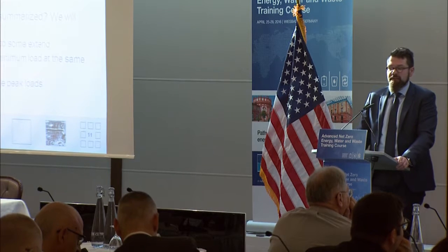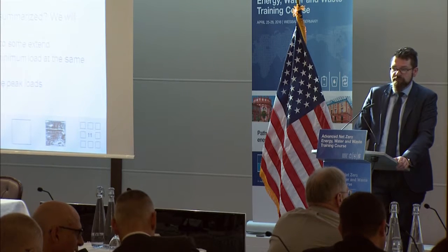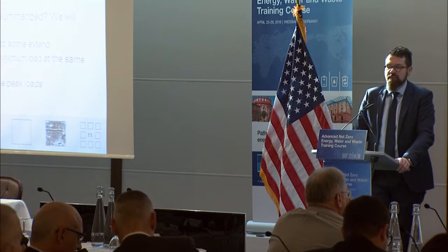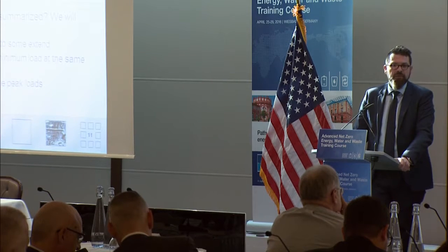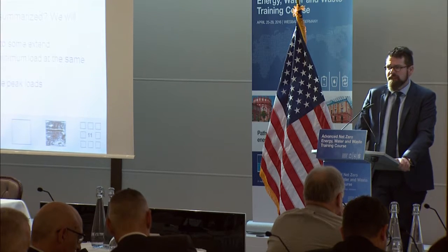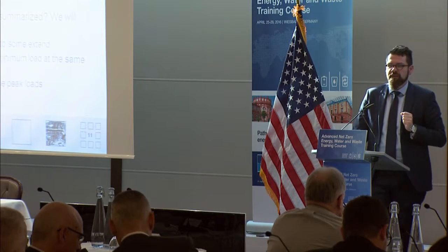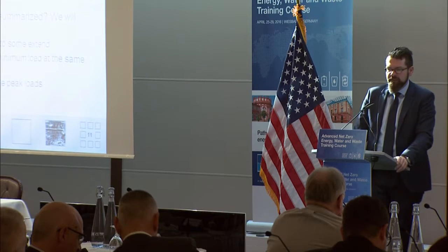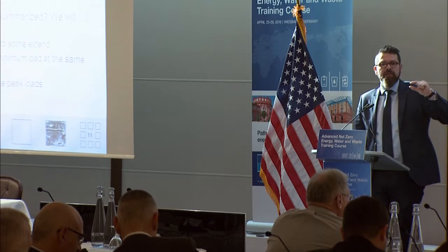Not all buildings have their peak load and their minimum load at the same time, and the total load, when you summarize it, is less than the sum of the single peak loads. This is a very important thing. If you have 3 buildings with, for instance, 100 kilowatts each, and you put them together, and the peaks are not at the same time, the peak load is not 300 kilowatts, it's, for instance, 250 kilowatts. So the minimum load is a little bit higher, and the peak load is a little bit lower.